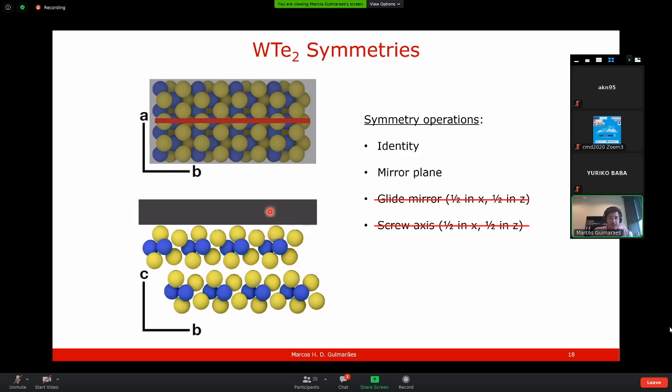Yes, that's true. The spin-orbit torques will be affected quite a lot by the spin transparency through the interface. So, for example, with the spin Hall effect, one naive way to think about it is that if you create spins in the tungsten ditelluride, you need to transmit them into the ferromagnet, and if this interface is very bad, then the spins cannot go through. So it is very difficult to make these types of devices, as I think you know. Sometimes we do get poor interface qualities.